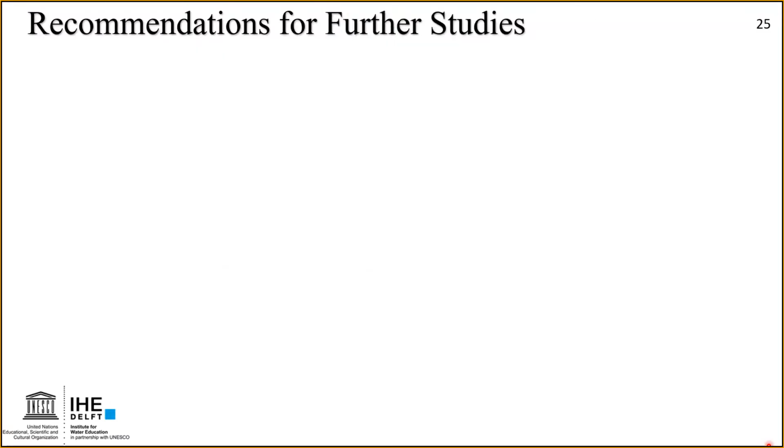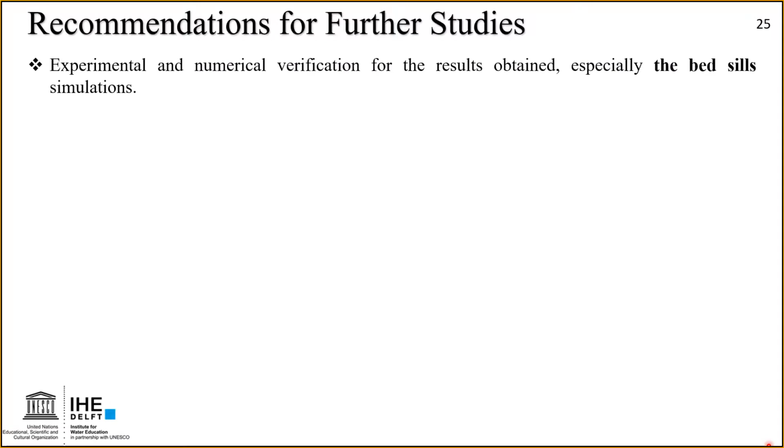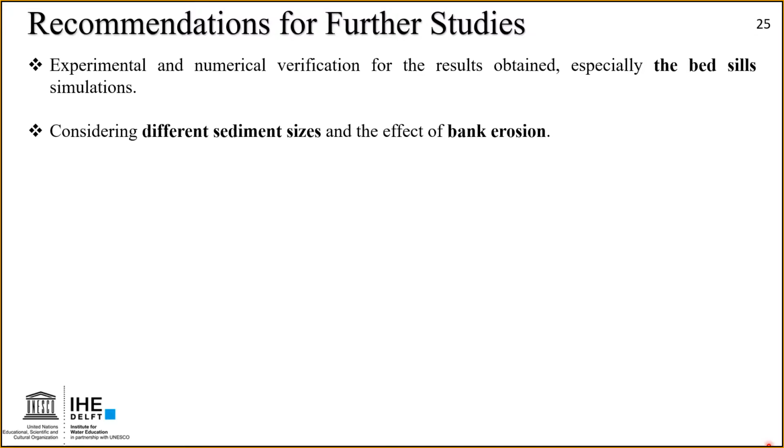Here are recommendations for further studies. We need experimental and numerical verification of the results, especially the bed cell simulation. Because the bed cell simulation, we simulated only as a local weir in Delft3D, which is a subgrid structure that only represents the energy loss that happens due to the bed cells, and puts it as quadratic friction in the momentum equation. So we need a better simulation to verify these results.